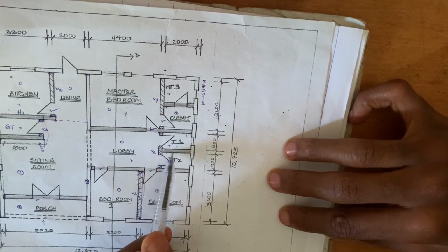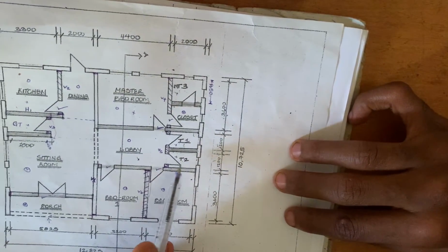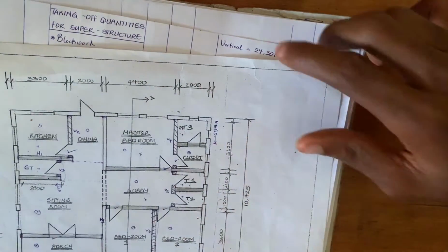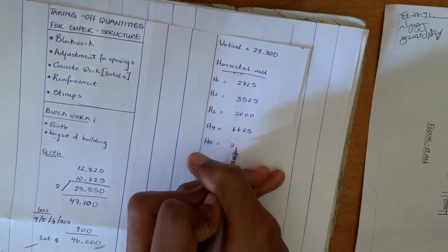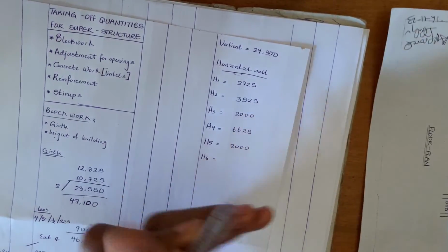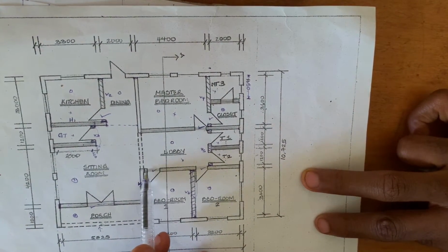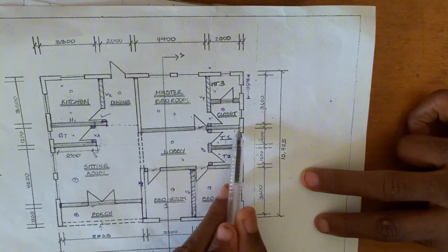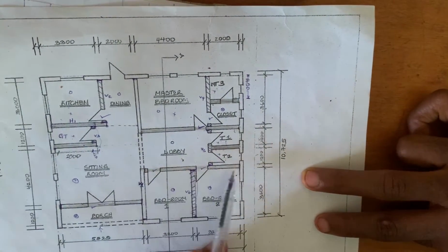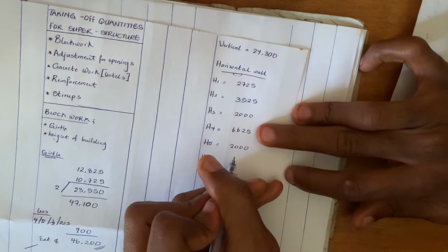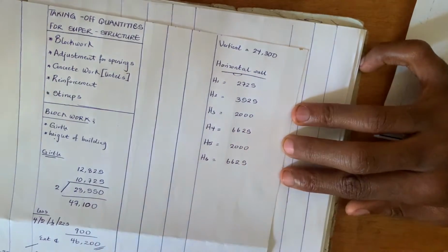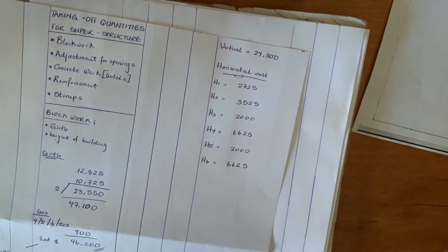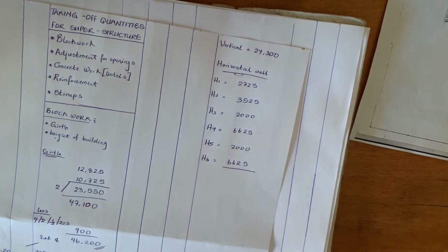Now H5 will be the block work dividing toilet 1 and toilet 2, which the dimension would be 2,000 as stipulated in the dimension here. So H5 will be 2,000. Then we go to H6. Now H6 is the same dimension as H4. That's this block work from here to here. We've already calculated it. So since they are the same, all we just need to do is to write it down as 6,625. So we've already found all the horizontals. That's 1, 2, 3, 4, 5, 6. That's 6 horizontals. Then we're going to be looking for the total of this horizontal,